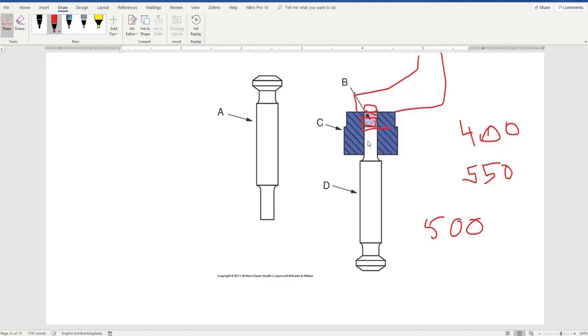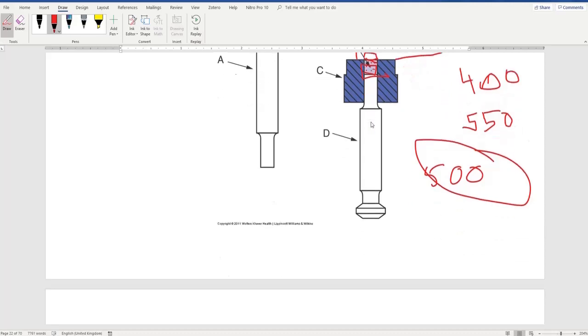When it does that, the lower punch goes down to the previous position to fill another 500 milligram of the powder from the shoe. And then the cycle continues. The shoe goes back, the upper punch goes down, and the compression happens again.